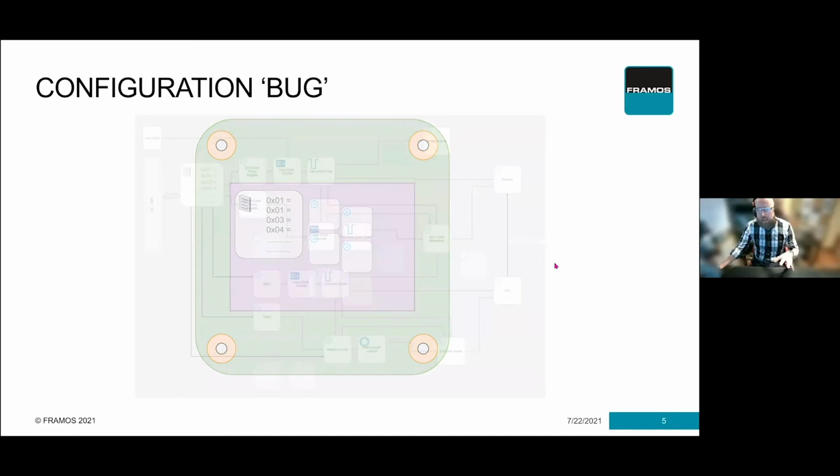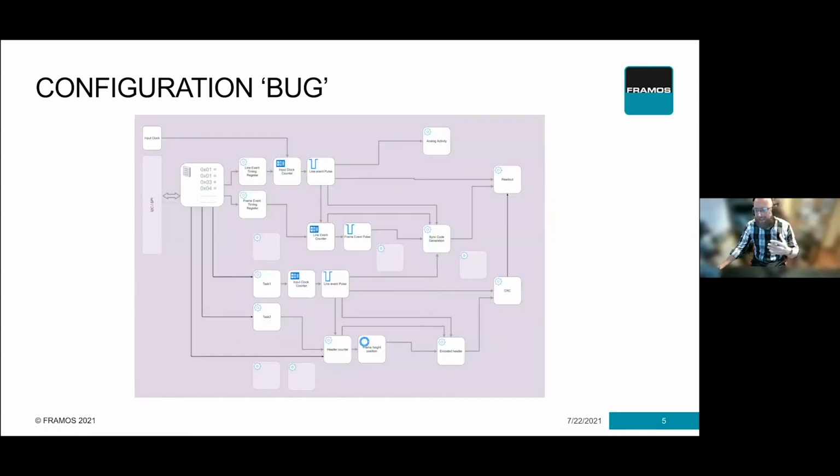Just to illustrate that, this is a representation of just what you would do with a line pulse. So for example, you give a line pulse to an image sensor to tell it to change lines. That actually drives a huge number of things, including this very innocuous looking little process here called analog activity. But the key is that multiple register values are used by multiple small sections of logic within the image sensor, a state machine, if you will. And those all have to combine and work together at the output.